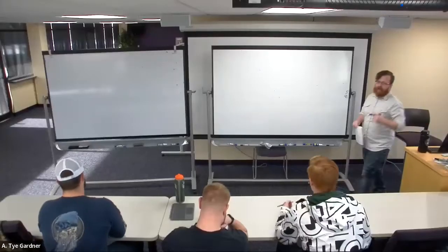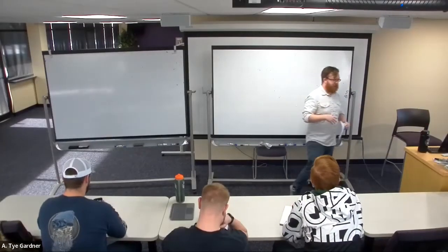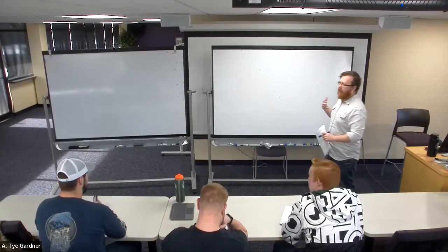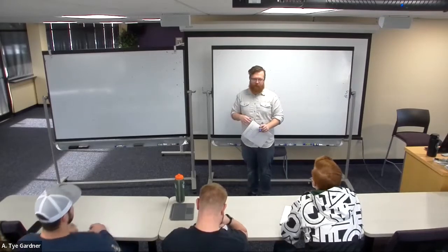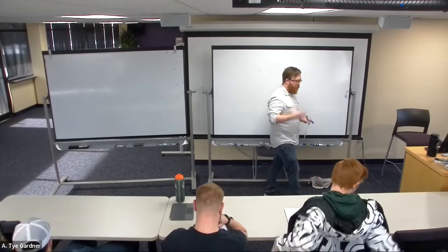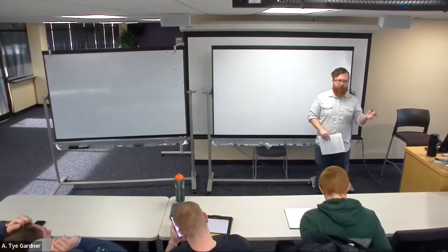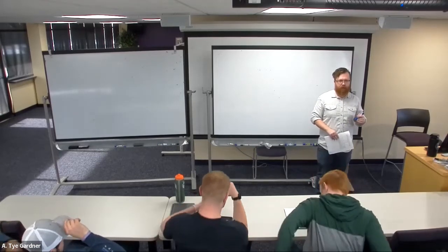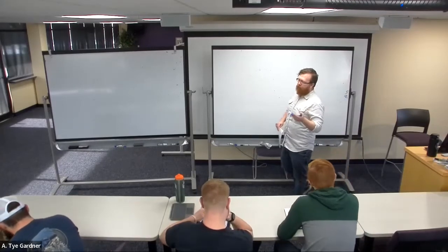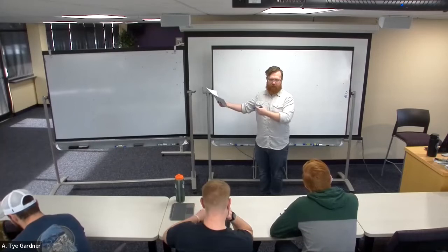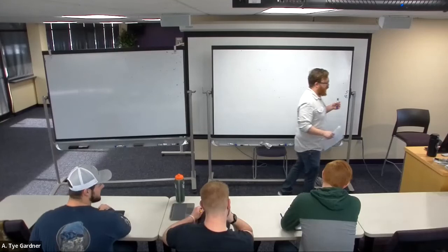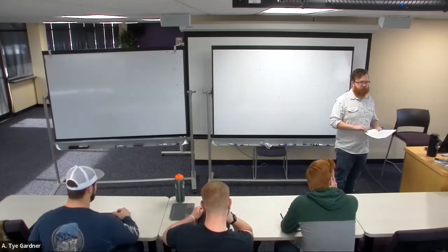Okay, so today we're going to move on to a new concept, I guess we will call it: how do we design circuits that remember? How to design circuits with memory, right? Because up till now, everything we've done is combinational, which really means the outputs depend solely on the combination of the inputs. Circuits with memory we call sequential, because they remember what came before in the sequence, right? So we're going to start talking about how we design sequential logic starting from combinational logic blocks, right?